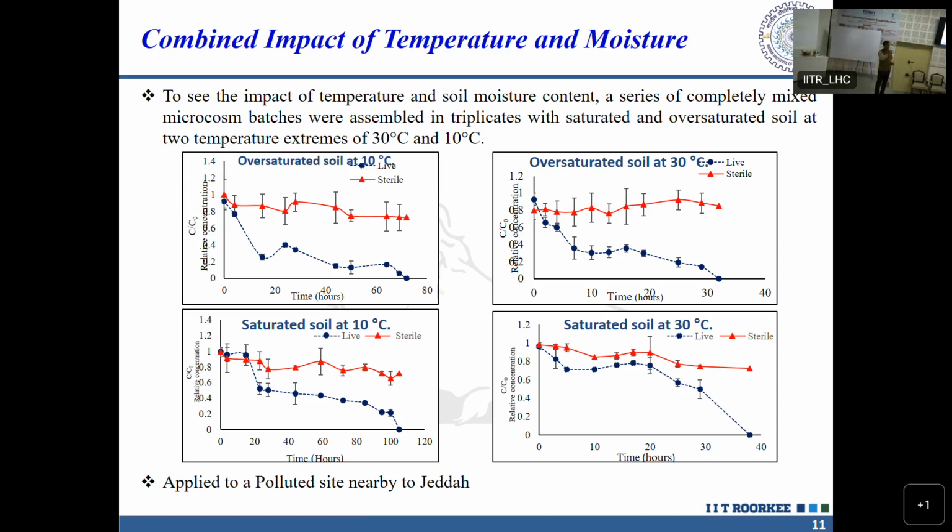For very dry soil, the degradation of the pollutant is going to be slow as compared to a moisture level near field capacity, where water is also there for the microorganisms, and oxygen is also there. So if we can maintain those favorable conditions for the microorganisms, of course, you can increase the rate of biodegradation. Or if the site is barren, you can suggest using specific plants which can target those contaminants. They can physically remove and also degrade those contaminants. That can also be applicable.